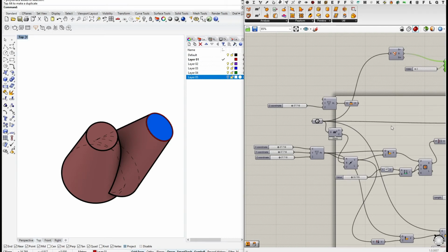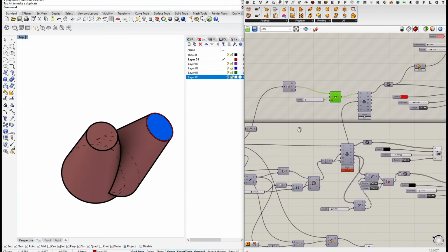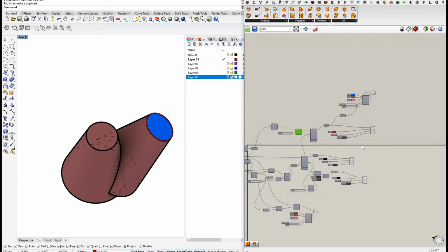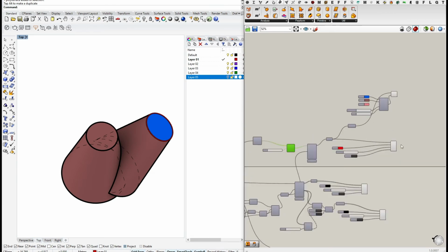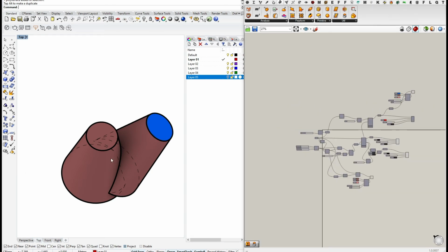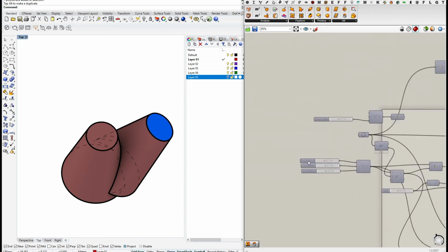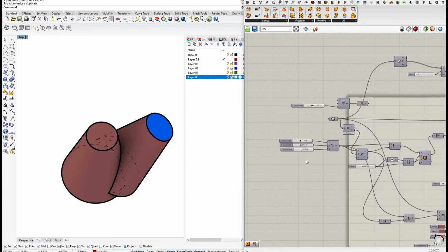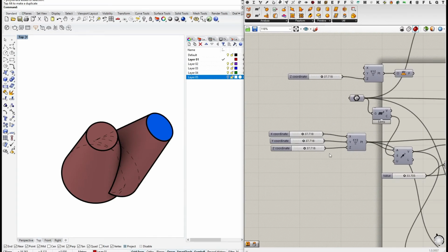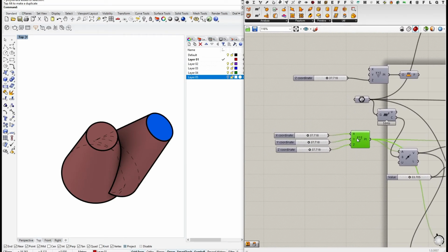So now, as a last step, we're going to look at slider animation. For this purpose, we will quickly hide this line work maybe, otherwise we keep our style the same. And we have now to make a decision, like what is it actually that we want to animate. I think for the purpose now of the tutorial, we will simply animate our camera viewpoint that generates the make2D drawing.